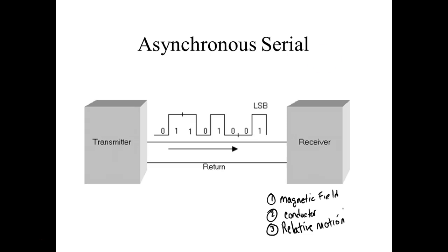Now it's going to be really small. It might be a microvolt. So we wouldn't even be able to measure this with a meter. But what we do is we come over here and we loop the wire. So that means when the magnetic field cuts 2 of them, then instead of getting a microvolt, we get what? 2 microvolts, because it would be like doing this.